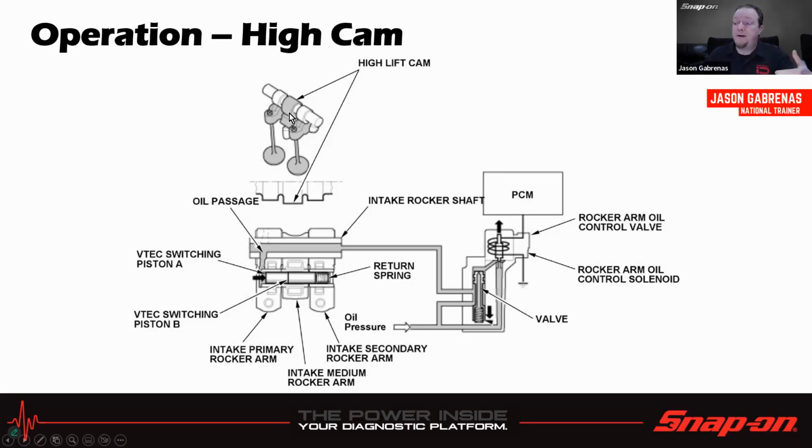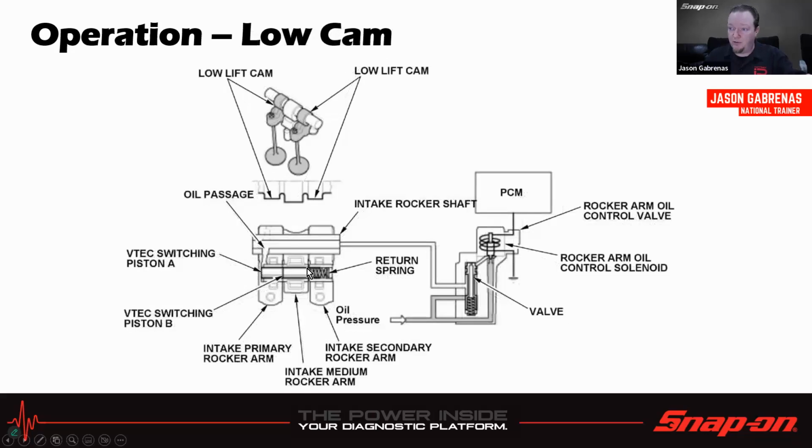So when it's just sitting there off, let me back up a slide. When it's sitting there off, this pin in the middle is not doing anything. It's just sitting there, and that high lift cam is still obviously going to be turning, but it's just kind of flopping around in the breeze. It's not directly connected to a valve.